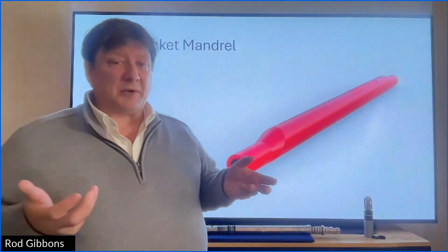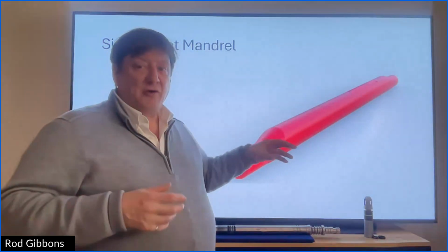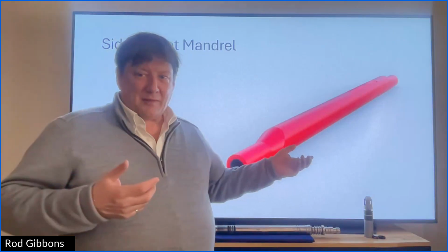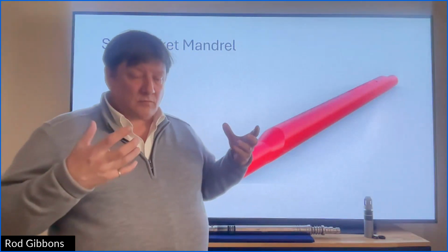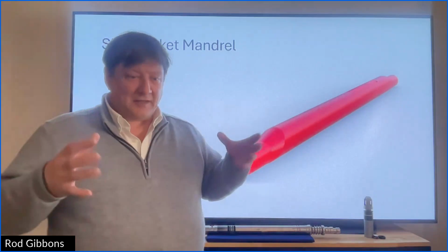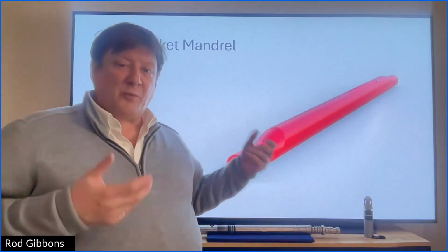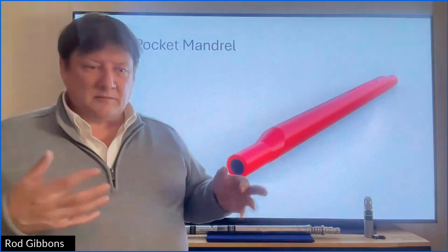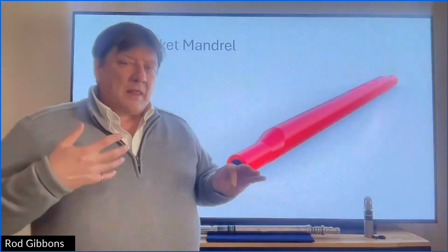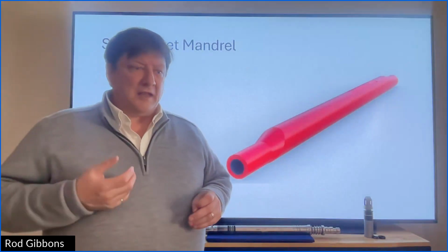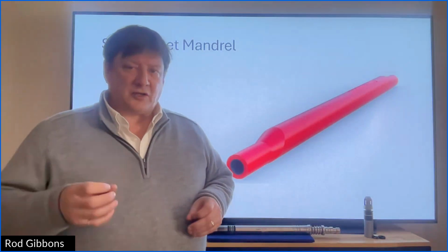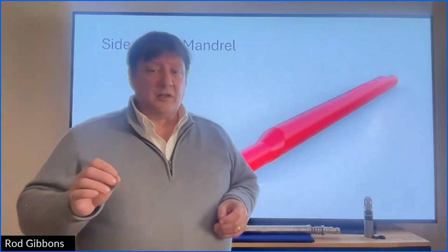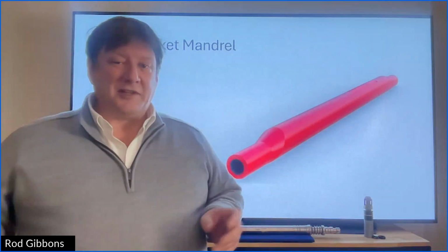So on initial completion, you'll run the mandrel with the tubing string. Before the mandrel gets in, you'll have just your casing, and the mandrel's run with the tubing. So you can have communication tubing to annulus, if that is a concern. At that time when you're running your completion, you shouldn't have reservoir fluids in your wellbore.